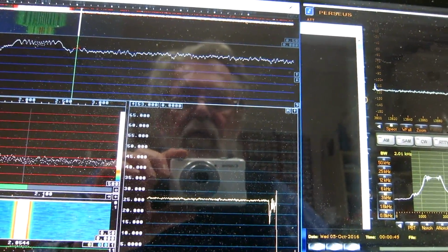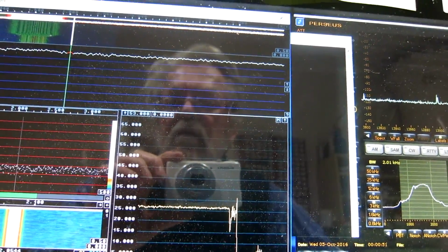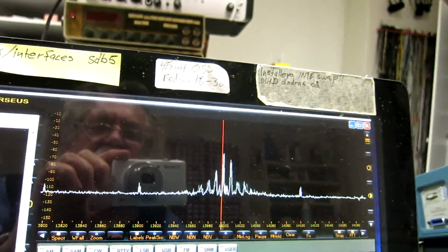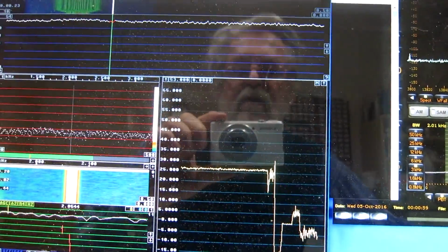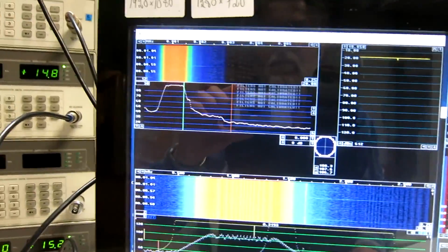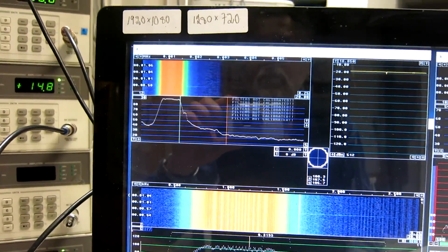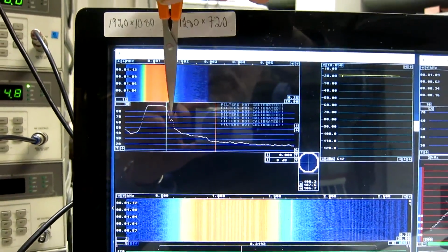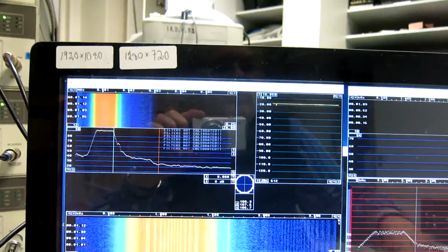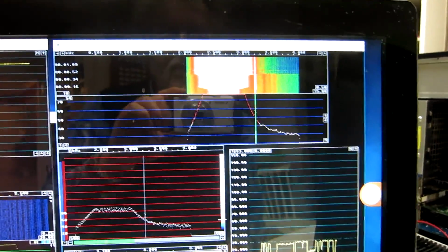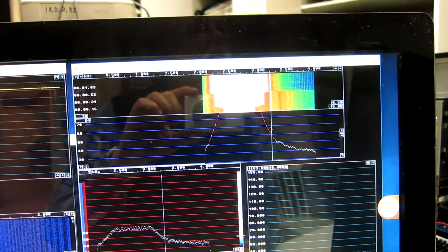And at this point it's hopeless, there is saturation. So at the point where the Perseus saturates, the ft1000 has big interference, but we can still see the signal here. And I cannot use the S/N measurement because Linrad isn't really written for this.